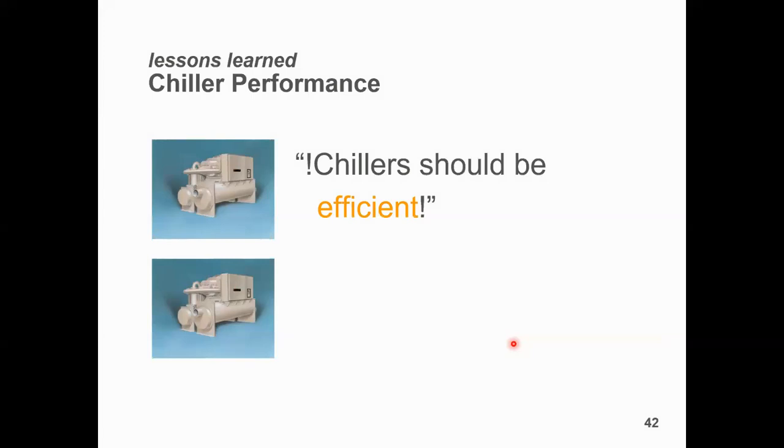Now people who want to optimize the operating cost, or are more focused on the operating cost, can put in a more efficient chiller by spending some more money on the chiller and make it almost at par efficiency even with 41 degree temperature. That is still possible. Or people who want to focus on the first cost can keep it as it is, because anyway there is still a savings.